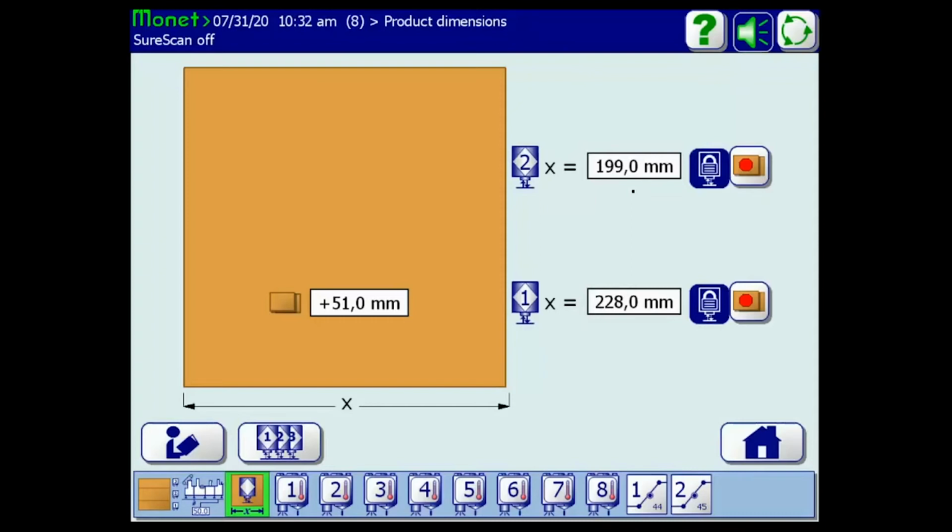That's why it's always preferred to keep your triggers over solid panels if you have the opportunity to. That way you don't have to worry about utilizing the lock feature. But I see what you're getting at. If the front 2/3 of a carton was missing and my lead edge reference was actually the last third of a carton, what I would assume would happen is you would fail because of gluing and detection.